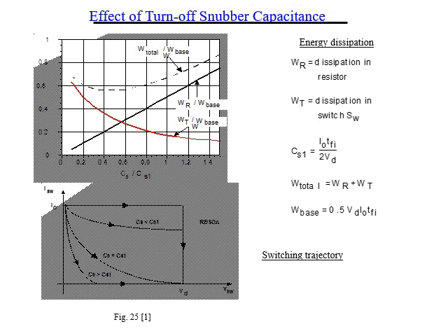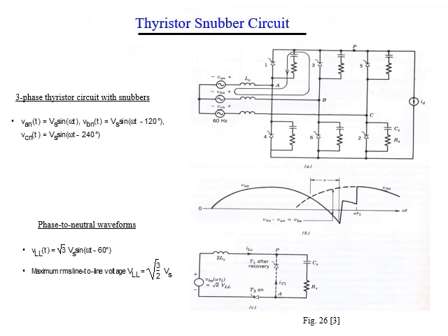Okay, so the total power dissipated is adding these losses together. Now, if I use one circuit, which is a rectifier circuit, a fully bridge 6-pulse rectifier, then for each thyristor, as you can remember, we have thyristor 1, 3, 5, 4, 6, 2. For each one of them, I will connect a capacitor and resistance in series as a snubber circuit.